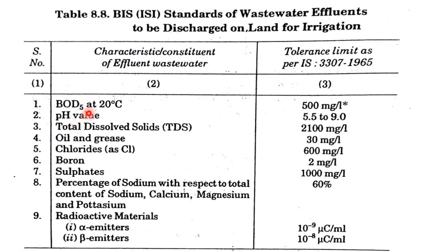It will give us an idea. BOD means the demand of oxygen required by the bacteria to stabilize the organic matter under aerobic condition, to digest the food which is present in the sewage. You can identify how much time is required and see whether it is capable or not. Those can be determined in the laboratory.